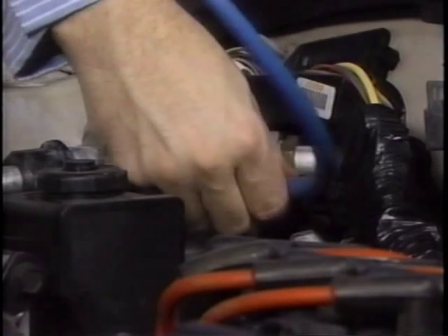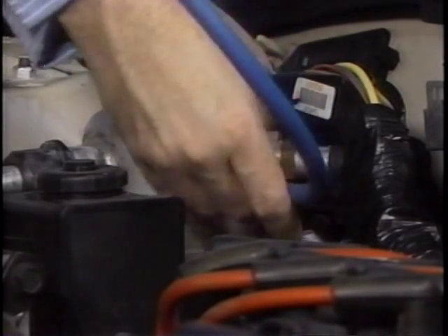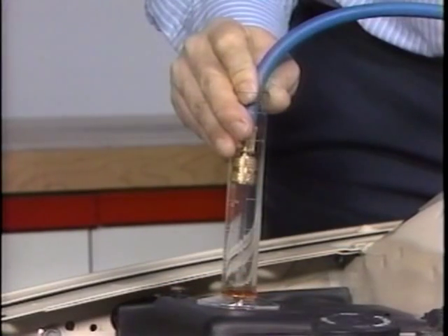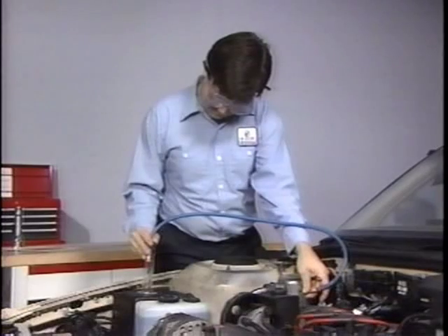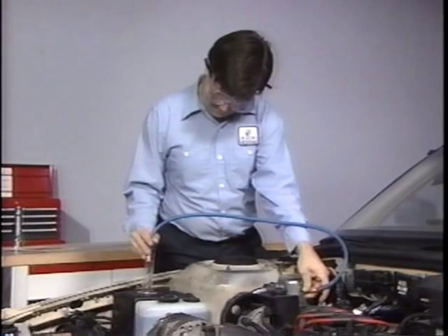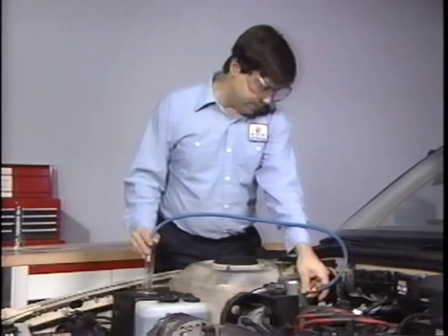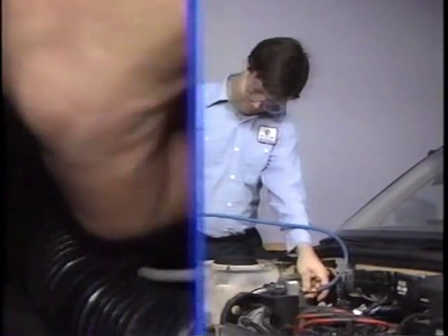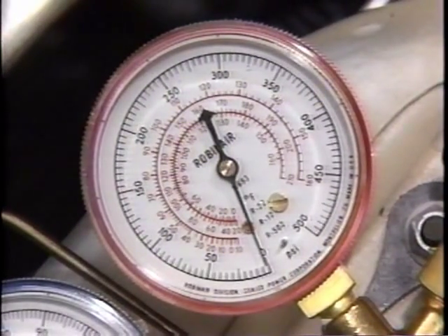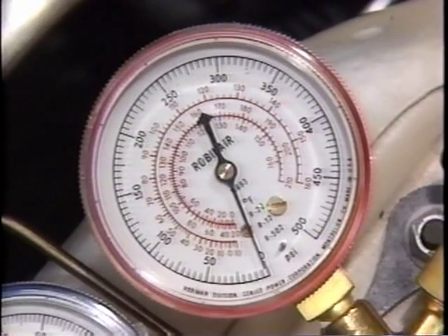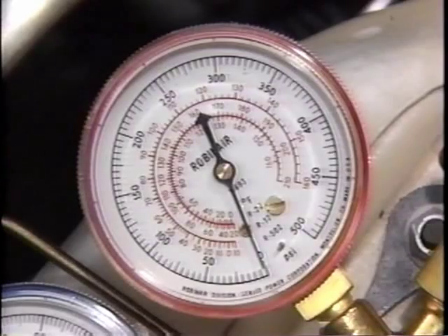Begin by slowly connecting a gauge hose to the low side service fitting on the accumulator, with the other end of the gauge hose inserted into an uncapped refrigerant oil bottle. As the hose is tightened, refrigerant will begin escaping into the bottle. If it doesn't, the Schrader depressor in the hose fitting may be defective or missing, and you will have to use another hose. With the system completely discharged, check for pressure at the high side fitting, located on the liquid line or on the muffler. Presence of pressure at the high side fitting indicates a restriction on the high side of the system, which must be corrected before evacuating and charging.